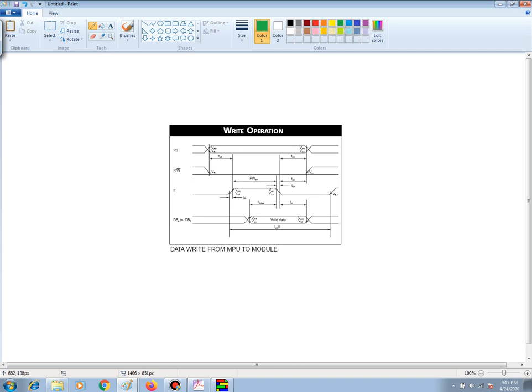Now what needs to happen? Well, let me explain just a few things here. I want to make sure that it's crystal clear. Whenever you see in a signal, like right here at this spot, something that is crossing like this, it means that there is a transition that can occur. This is where that line can change state. After that, during this phase right here, that's where the RS line needs to be stable. It can be either a high or a low, but it really needs to just stay steady.